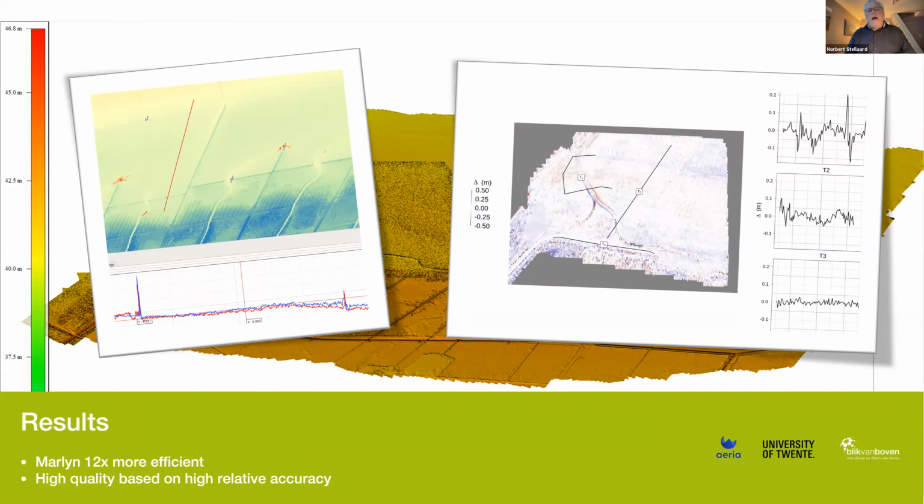On the right, you see a set of data in which we do various kinds of measurements. The T3 one, that's the dike. We have a dike there, and if you put a line on that, it has to be almost flat, as you can see. So, to summarize a little bit, we found a very good accuracy in the relative way, more than we expected, very high. 54.5 centimeters we measured on an original thing of 54 centimeters. So that's perfect.